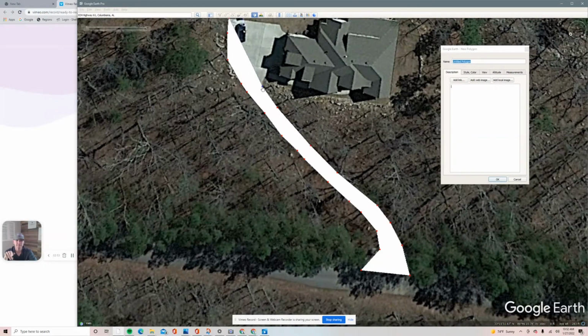All right, so right here we've got a sidewalk that goes up the front. So we're actually going to measure this all in one measurement. We're not going to take separate measurements because we always estimate the sidewalks along with the driveway. So pretty much all flat work is the same, so we just measure it all at once. So we're going to go down the side of this little sidewalk. And then we're going to go across, and you're going to use the same method I showed you earlier.